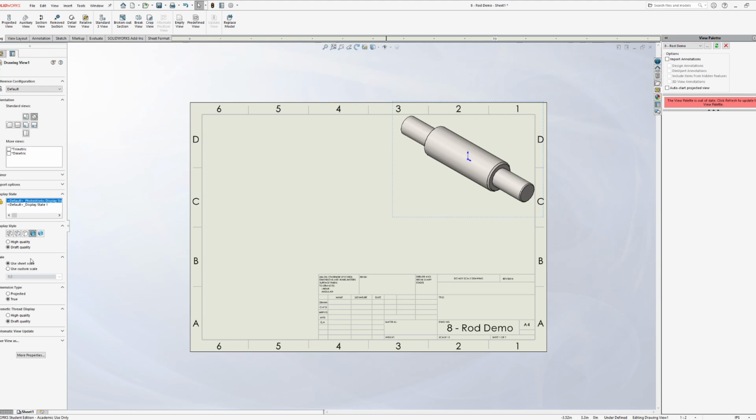We also, if we wanted to, have a scale option on the left-hand side. So we could use the sheet scale, which is whatever we choose down here at the bottom right, but we could also adjust the scales differently per whatever kind of thing we might be working with. Sometimes some drawings might need to be smaller than others. We might not need to use the entire drawing there, or rather a 1 to 2 or 1 to 1 drawing. So sometimes we want to either scale things up or scale things down.